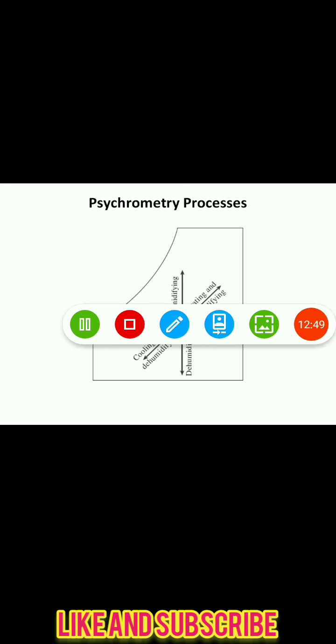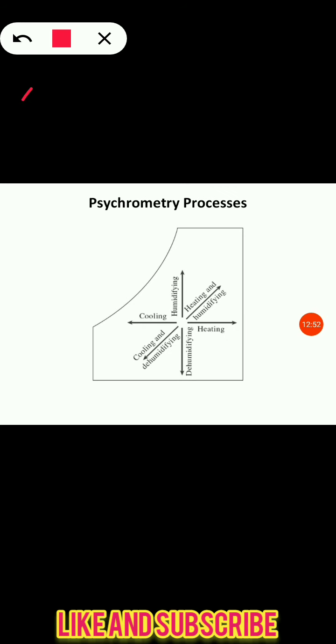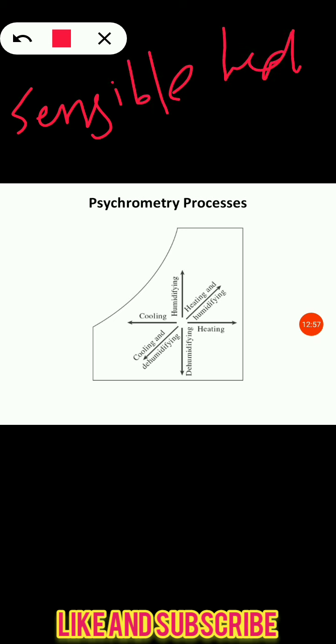So here we can see there are different psychrometric processes like sensible heating, then sensible cooling. In the sensible cooling process, we generally decrease the temperature of air, that is, the dry bulb temperature decreases. In sensible heating, the dry bulb temperature increases. So in the sensible heating process, we need to have a heating coil in the air conditioner. In a sensible cooling process, we need to have a cooling coil or a refrigerating coil in the air conditioner equipment.